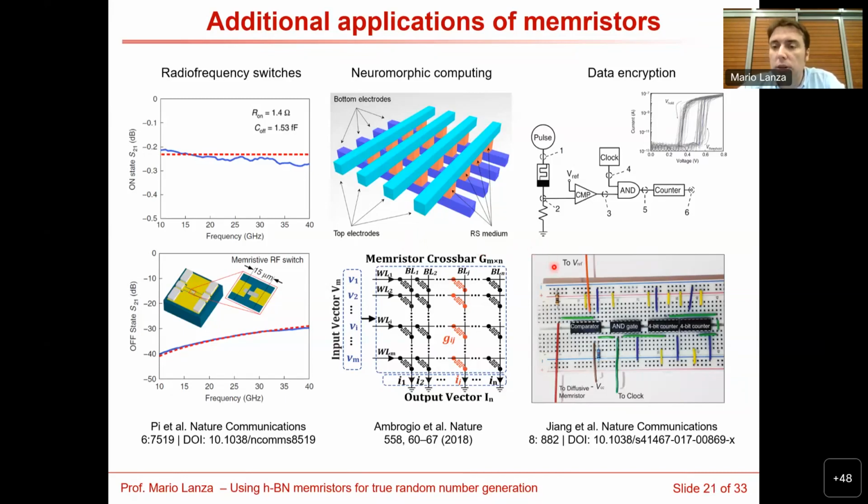And then the memristors also exhibit one property which is unwanted for memory, radio frequency switch, and neuromorphic applications. This is called variability. Cycle-to-cycle variability, like this, and device-to-device variability. This variability, as I mentioned, is bad for the other applications because you cannot recognize the state of the memristor if there is variability.